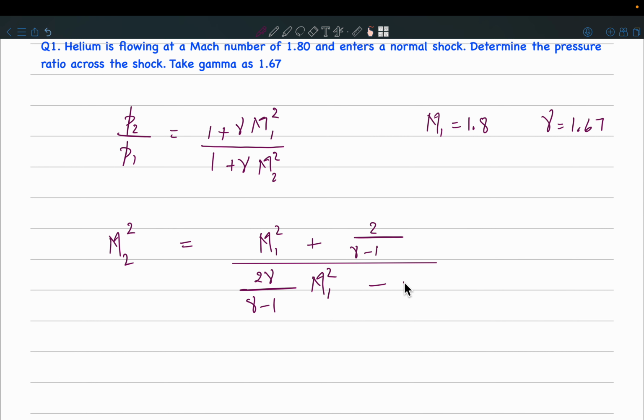You can either use gas tables, always keep your gas tables handy, that would be better. How are you going to use the gas tables, by the way? Do you have gas tables for gamma equal to 1.67? Yeah, okay. So you're saying that M2 is, can you repeat, 0.6? Yeah, 0.9. Okay, so I can write 1 approximately. Yeah, this is fine.